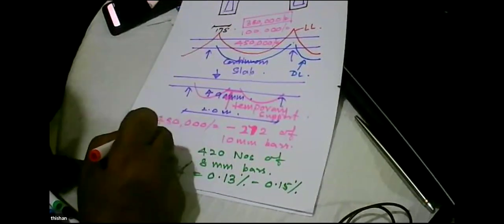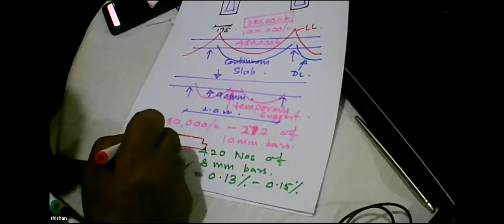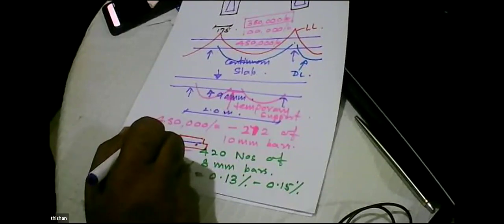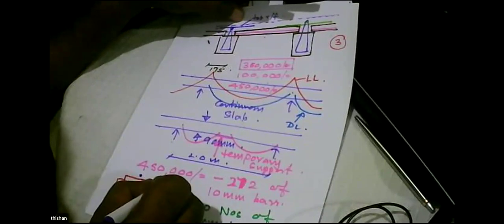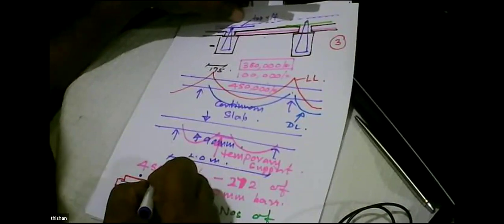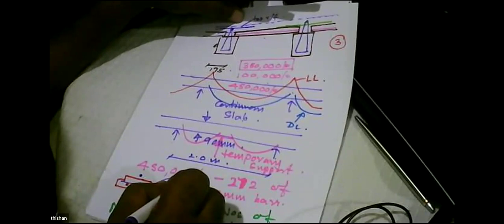Because we cast the slab like this. We place the other slab like this. We place 2 reinforcement like that. Then we place an additional reinforcement. And can you remember I said that we need a reinforcement for continuity? This reinforcement, the dotted line. So the reinforcement of the dotted line goes there. The continuity reinforcement goes at that place. So this will lock. This will make it continuous.